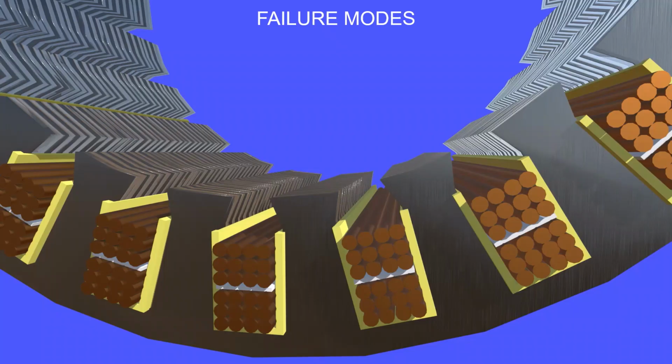First, turn to ground. Can ground wall testing interrogate this weakness and fault condition? The answer is yes, it can. Next is turn to turn. Can ground wall testing interrogate this weakness and fault condition? The answer is no, it cannot.